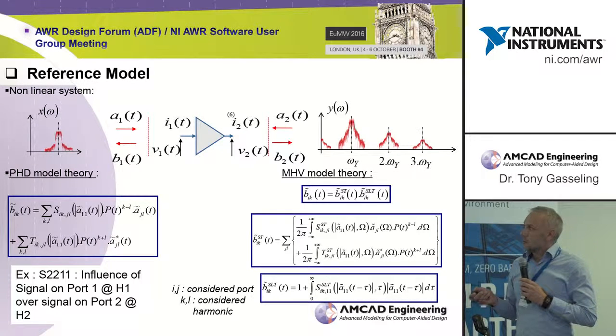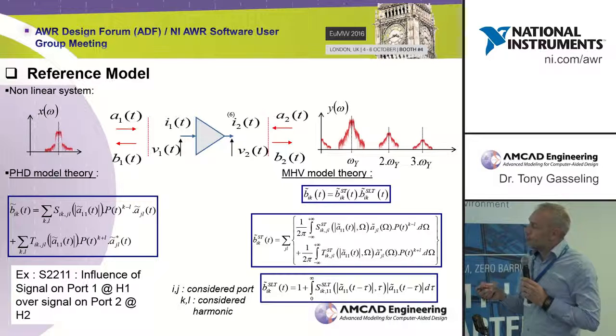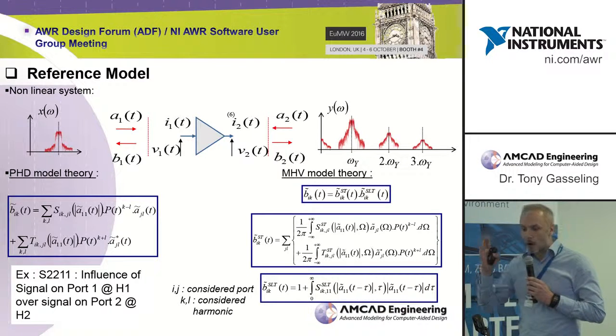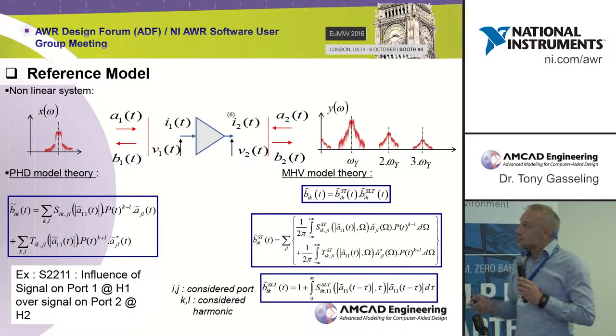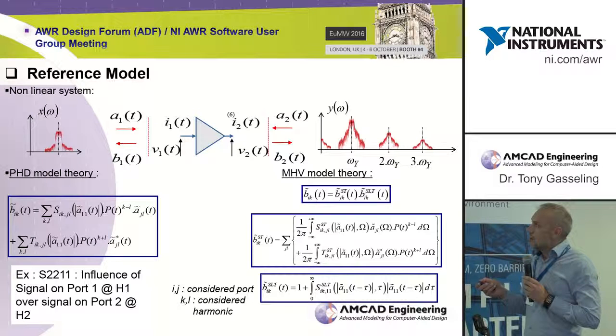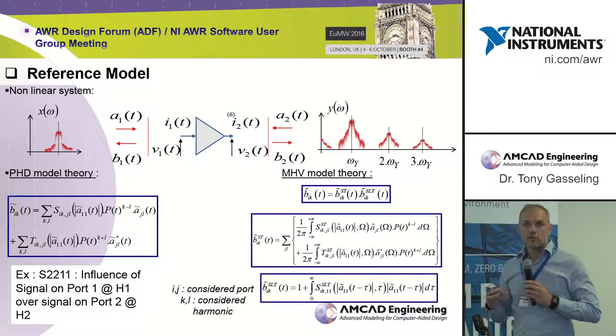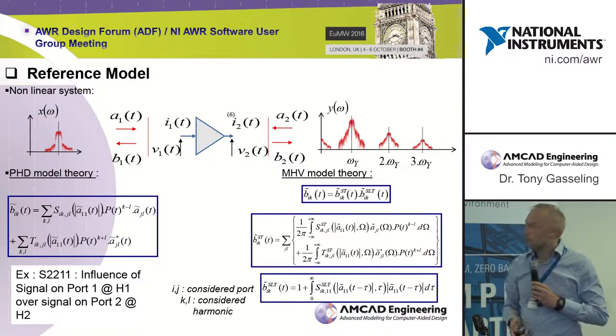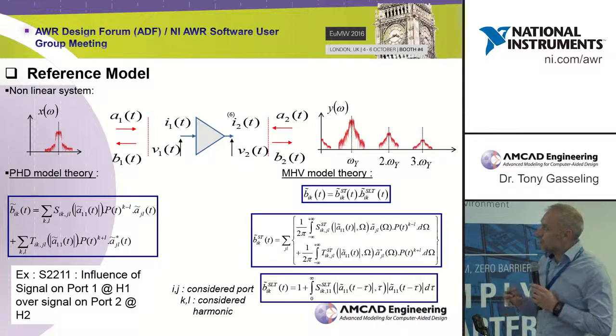So what we did here, in fact, is that instead of having a model which is just given for one frequency and all the harmonics, we rather try to work with a modulated signal. That is to say, we applied on top of these kernels some integral in order to make an integration of the model response over these kernels, which is a combination of the PHD approach and the Volterra series together. So we create some Volterra series on the kernels of the models. And this way, we are able to take into account wideband behavior in the model.